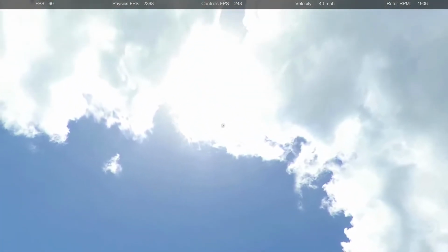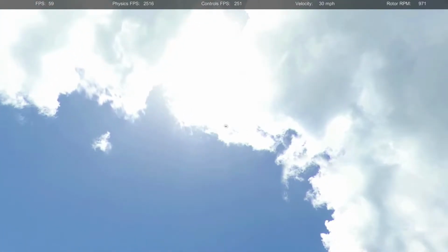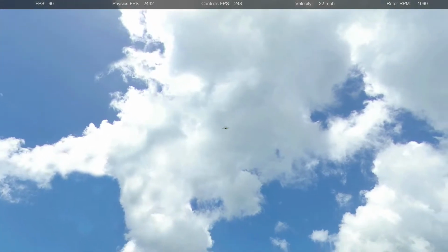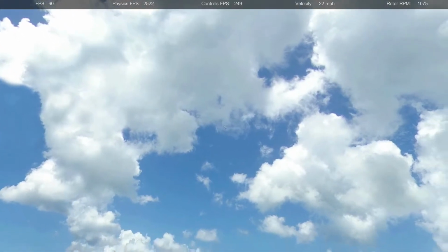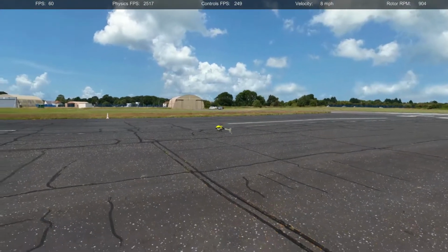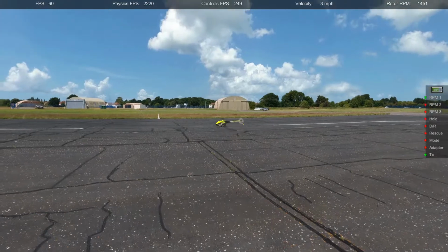So one other place we have to stop is Dick Whitcomb. And Whitcomb was the guy that came up with winglets. This was in 1975. And I need to explain this to you. When you put a winglet on an airplane, you don't actually change the location of the vortex. The vortex still happens at the wingtip. But what that winglet does is it takes a little bit of energy out of that vortex and it pushes the wingtip forward.